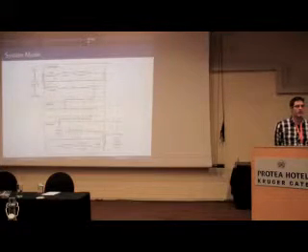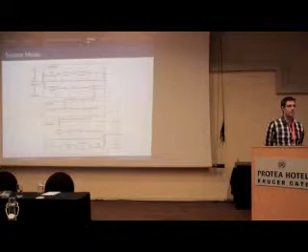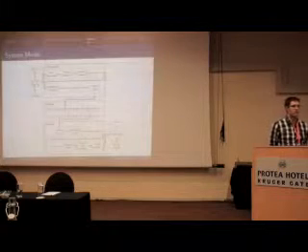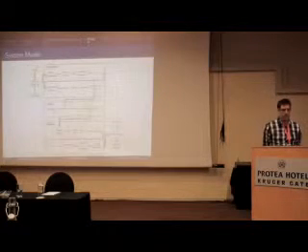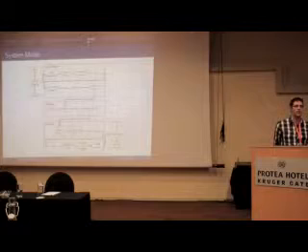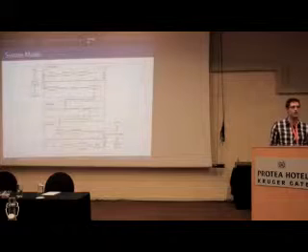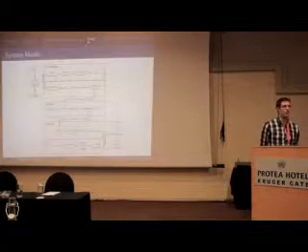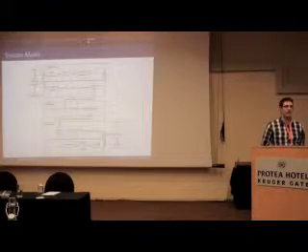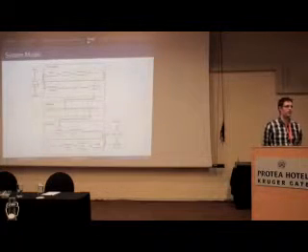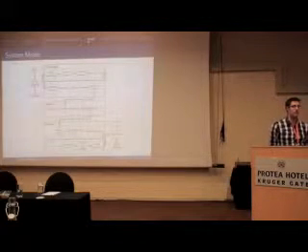Another problem is that you talk about something about the cyclic prefix length. I think that for the detection of the cyclic prefix length, it's not so easy. Do you have some method? Usually how it works with mine is the receiver will be synchronized, so we'll know the length of the cyclic prefix. I will know that it's set at 25%. That's what's commonly used, so I don't have to detect it, I can just take 25% from the receiver. 25% for what? I mean for the detection of the location of the prefix. Yes, that becomes another problem.